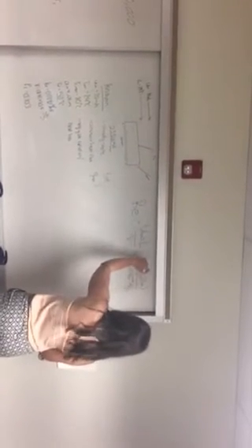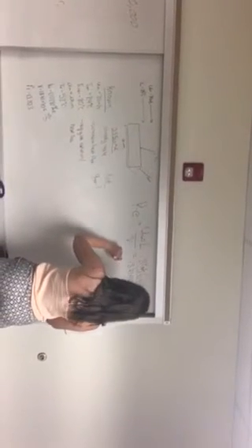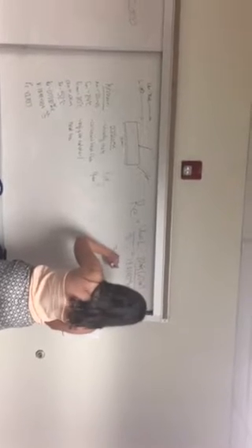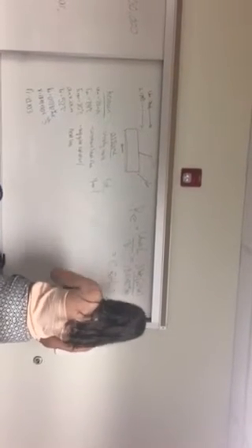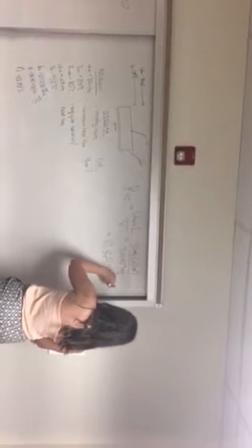All right, and then our units will all cancel out. Our Re value is going to be 10,864, and because this is less than 500,000, we're going to have laminar flow.